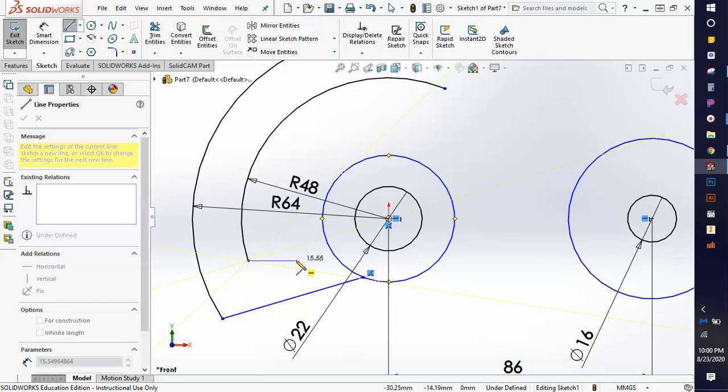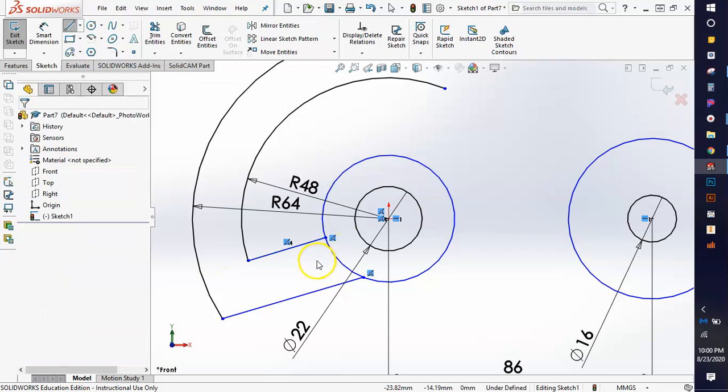You see it gives you a whole bunch of different projections, and this one projection actually has it taking it right to the origin. We don't want to take it all the way to the origin, but we do want to take it to this circle. And I'm interested to see that when we do that, what it actually did was make it coincident with the origin already. So it really saved us a step. I've never noticed it doing that before, so that's pretty nice.